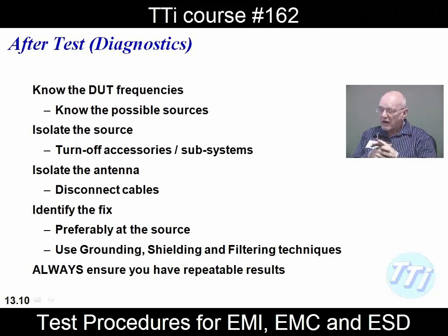Spectrum analyzer? Correct. A spectrum analyzer allows you to identify all these frequencies. Makes out pretty well from that standpoint, doesn't it? And of course, you need to isolate the source. Now, when you test this, like in the CE environment, you have to have everything around. But now we want to isolate where the problems might be. Remember, pre-compliance, you're trying to isolate the source to be able to get a fix for it before you send it out for complete compliance testing.